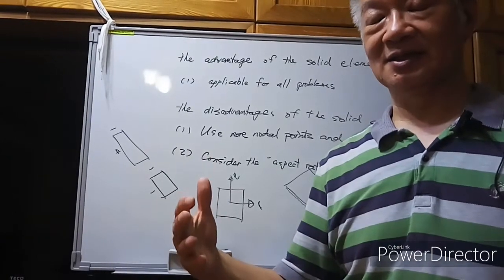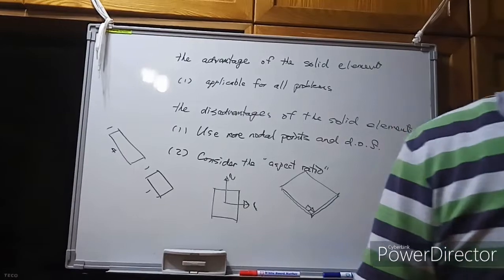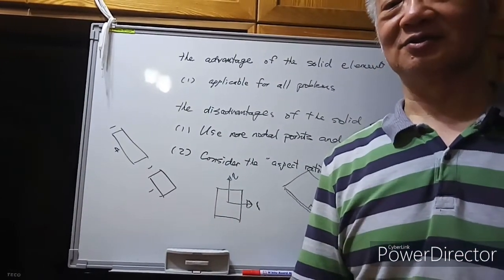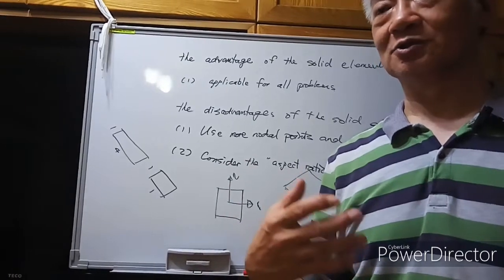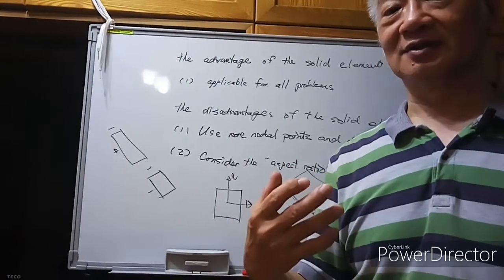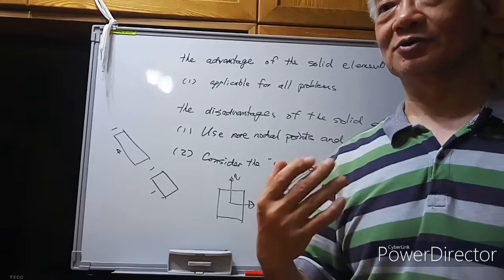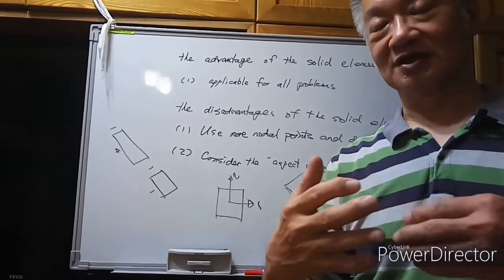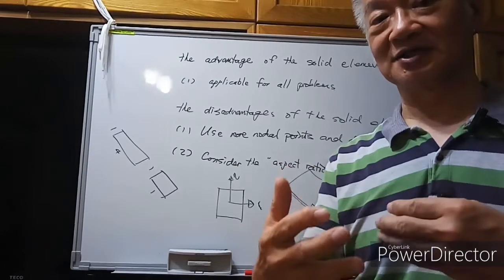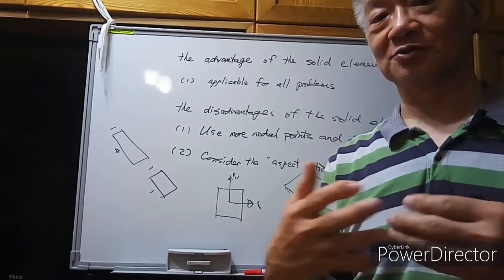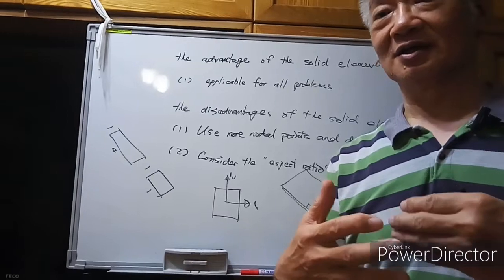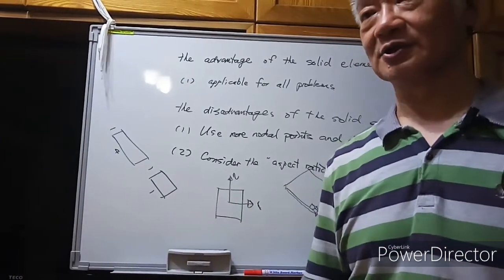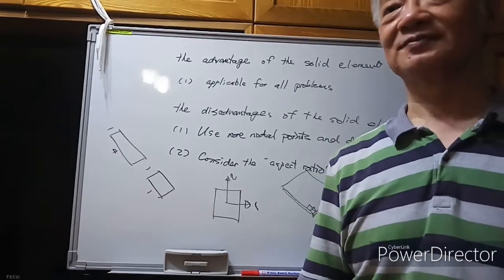So if you use solid elements to solve the problems, you can expect to spend a lot of calculation time. Also, you can expect more complicated mesh problems, since you need to define a lot more elements compared to other structural models.